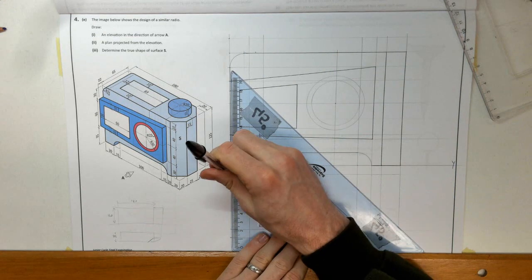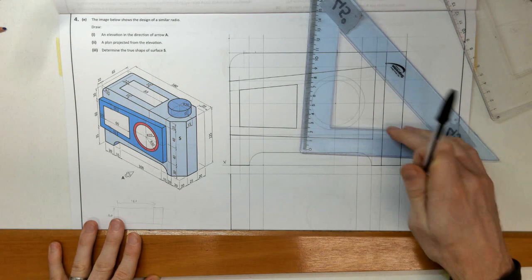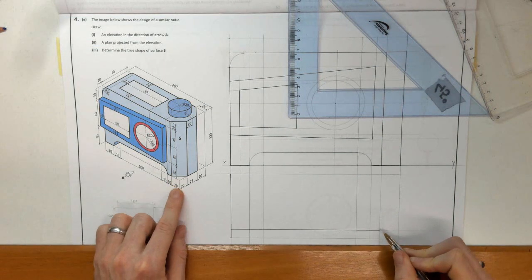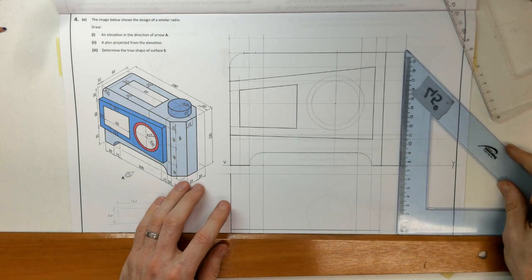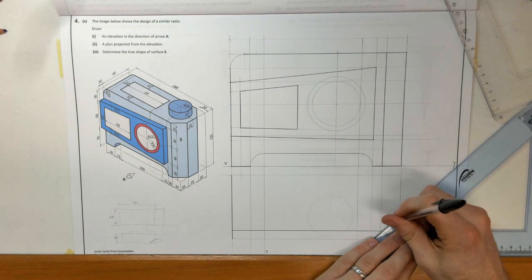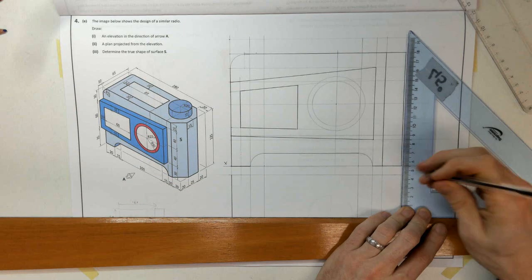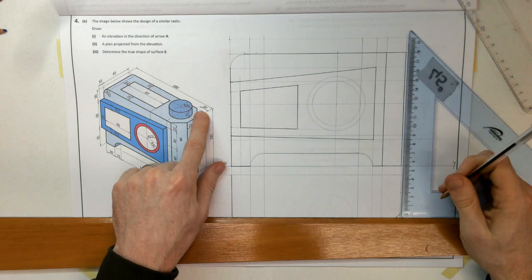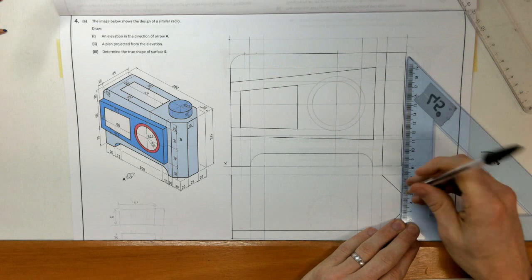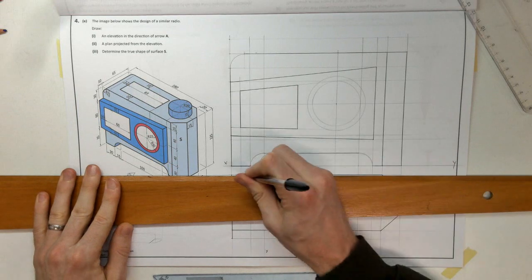So the outline is going to be heavy line. That is coming to here, stopping short because I've got my surface S going at an angle, which is 20 and 20, so I can mark 20 back this way. That's another measurement I could have done. And then coming 25, and that leaves 20 left over for that sloping bit at the back on the opposite side to S, and a chamfer, and heavy edge going back to start again.